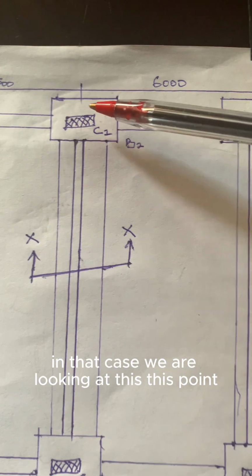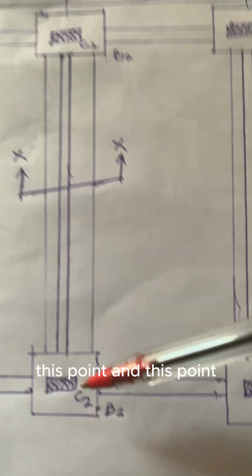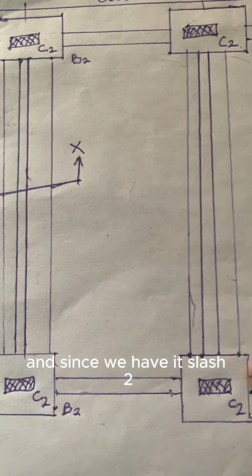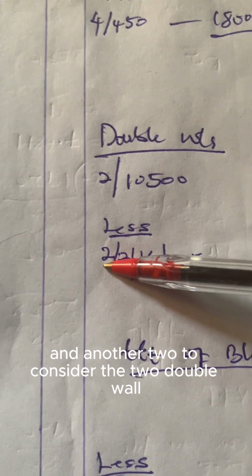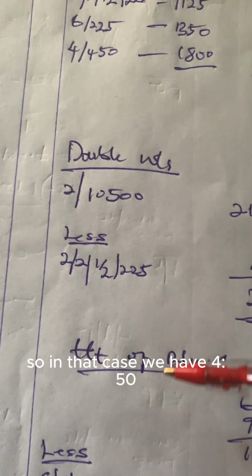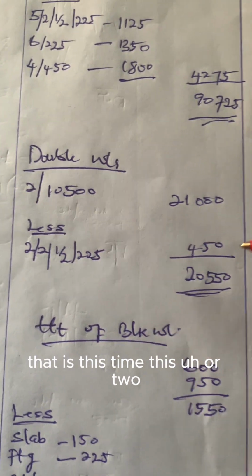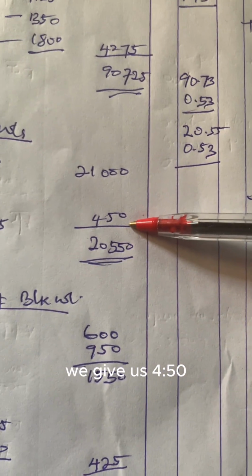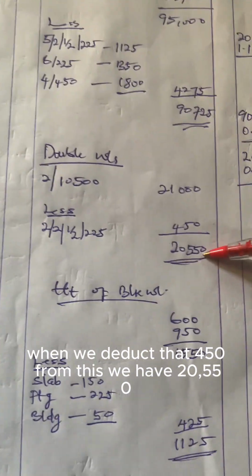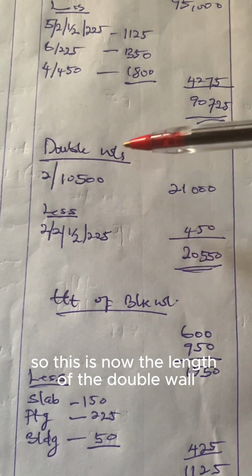In that case, we are looking at this point and this point. And since we have 8/2, that's why we slash it by 2 and another 2 to consider the 2 double walls. So in that case, we have 450. That is this times this. All through will give us 450. When we deduct 450 from this, we have 20,550. So this is now the length of the double wall.